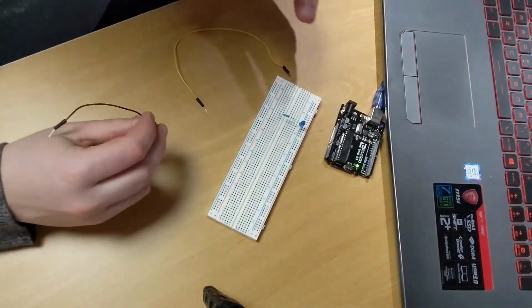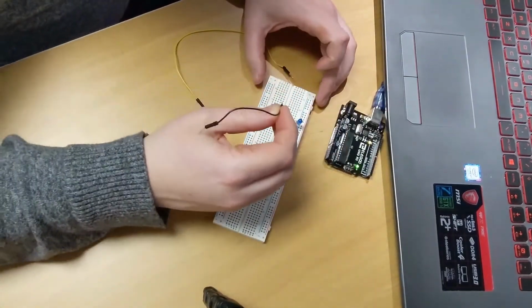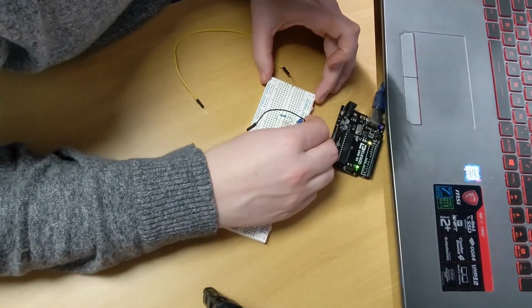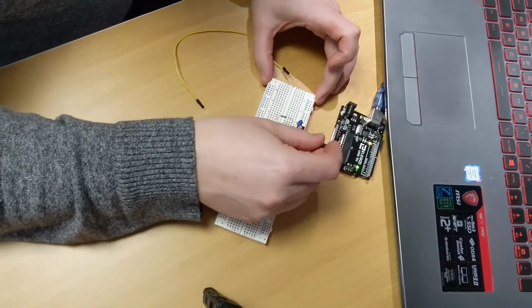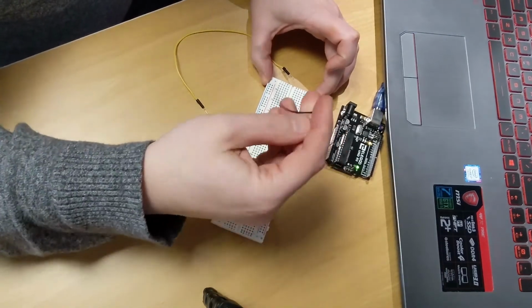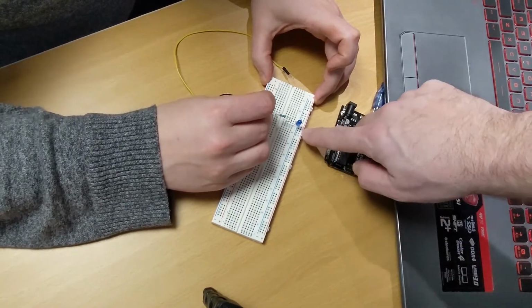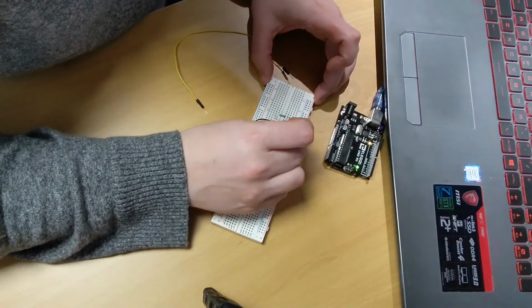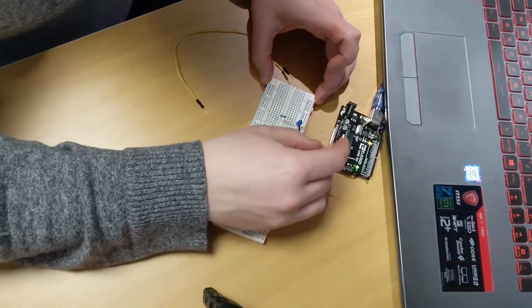Then I'm going to take my black lead, and that black lead is going to be connected up here into the same group as the LED. Oh, sorry. No, say that back. Sorry. So you're just putting it into where the positive goes. It needs to be on the same one and the blue one as the LED. Yeah. So put that in the negative side. Make sure it's on the blue side there. And I'm going to connect that into the ground.